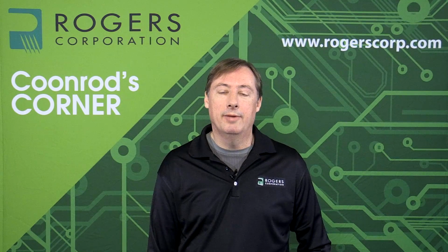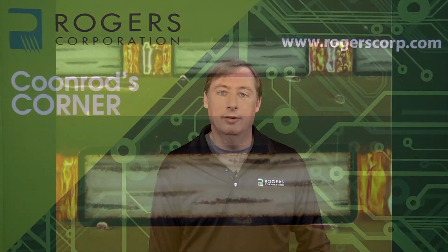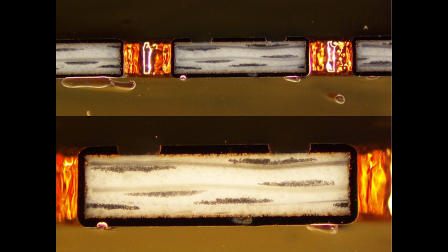The grounded coplanar waveguide transmission line has another influence, and that is the trapezoidal effects. The trapezoidal effects are a common influence for printed circuit board fabrication. If you look at a microsection or a cross-sectional view of a circuit, you'll find the conductor is not rectangular. It usually has some angled sidewalls, so it has more of a trapezoidal shape. In the case of the microstrip transmission line, the trapezoidal shape has very little influence on the impedance. But in the case of the grounded coplanar waveguide, it does have more influence on impedance.